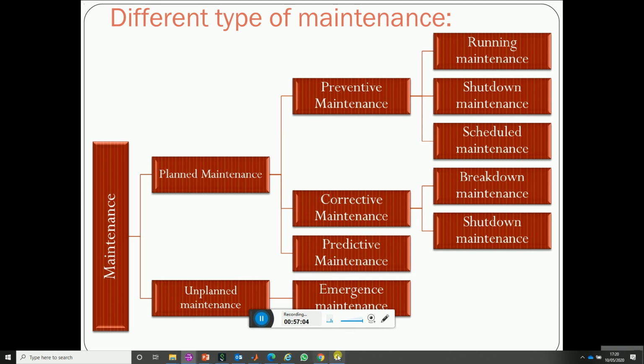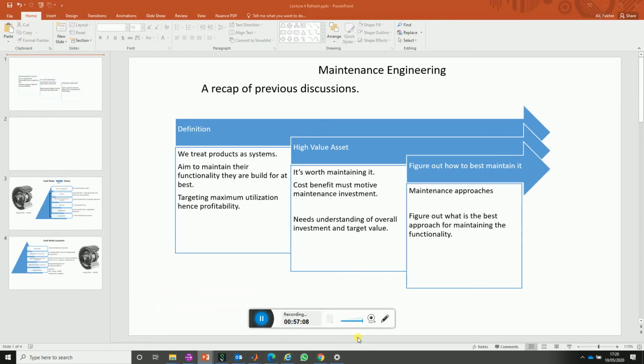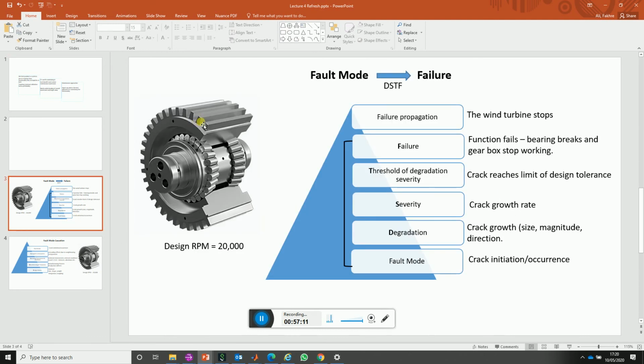So for example, in my bearing case, I have put an accelerometer, and I have installed a thermocouple, and I am collecting real-time data through a data acquisition unit from the wind turbine, and analyzing in real time if this accelerometer experiences vibrations more than the tolerance of this gearbox, or this bearing inner housing suffers temperatures more than I should be expecting, and then I can swiftly do something about it.